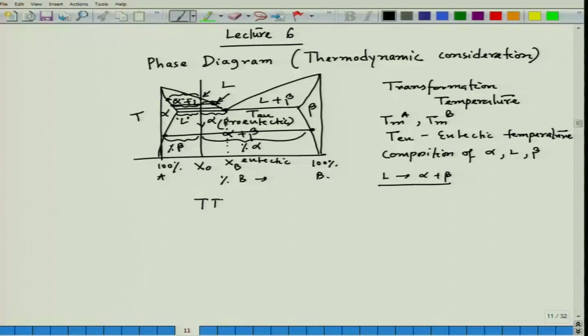and at the same time what are the composition as well as fraction of those transformation products. But during heat treatment we need to know the TTT diagram. So, that would decide my time and temperature, means how long I would like to continue heat treatment and at what temperature we need to do the heat treatment, depending on what sort of properties we would like to get from the final product.